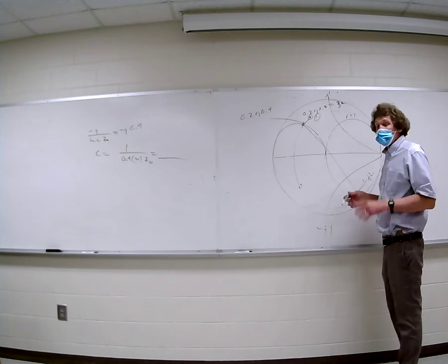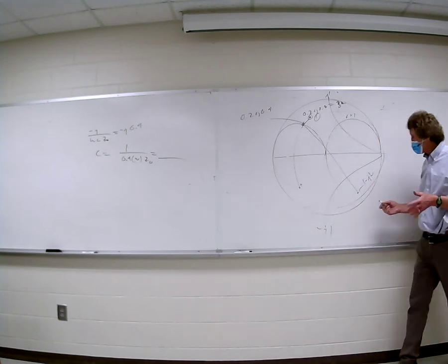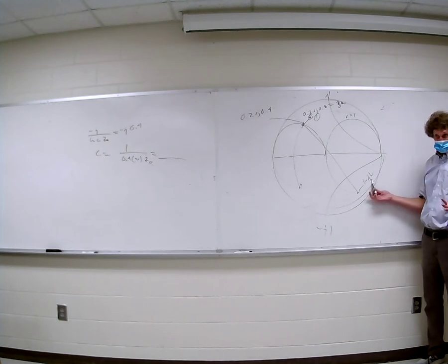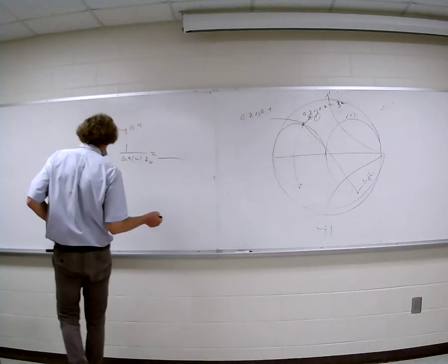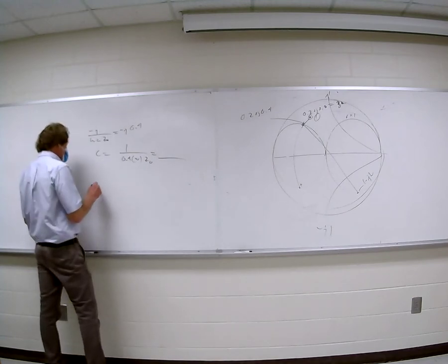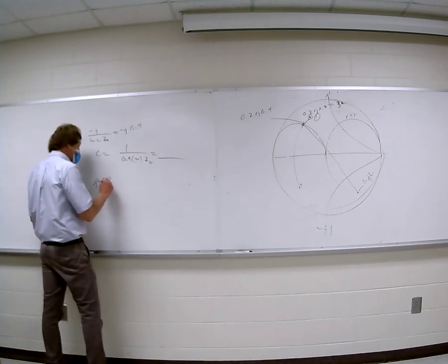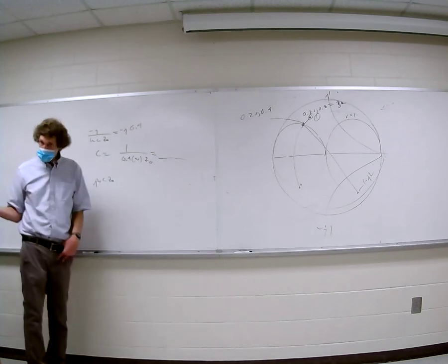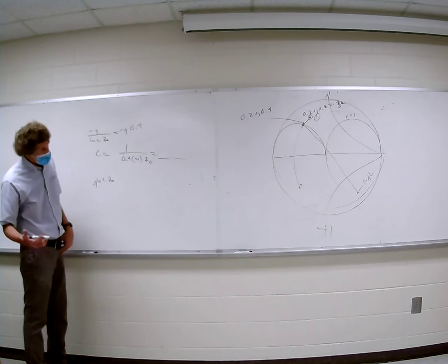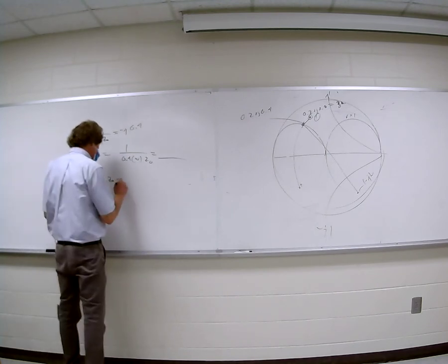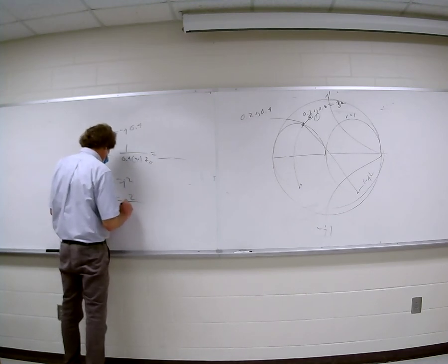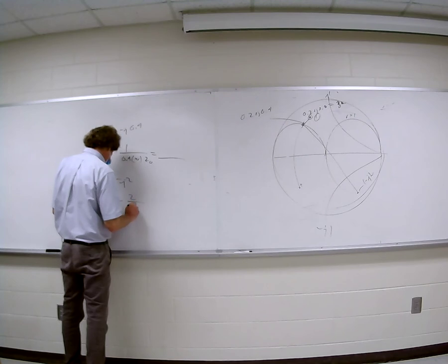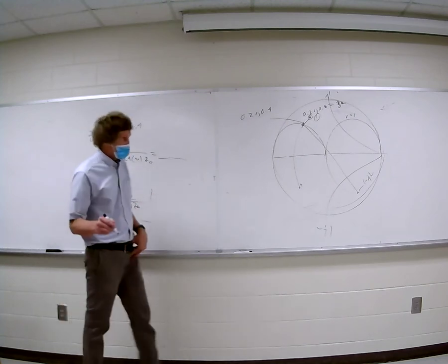All right. Now, that's admittance, right? How much normalized admittance do we have to add to get rid of this? J2, right? So, that's normalized admittance. Think about it. Anytime you see a positive J, you know it's capacitance. So the admittance would be J omega C, normalized by Z0. This is for the capacitor. We're putting it in parallel. You all agree with me? And that's equal to J2. Or we can say C is equal to 2 over omega Z0, and that is the capacitive value.